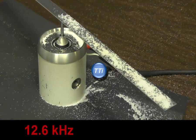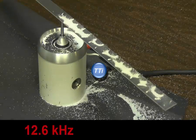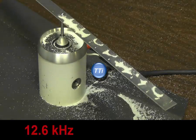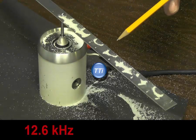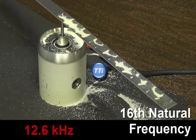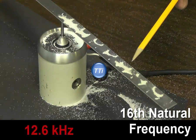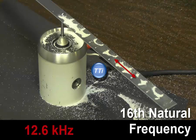Now we're driving the beam at 12.6 kilohertz. Let's apply the power to the shaker, see if we can find the nodal behavior. One, 2, 3, 4, 5, 6, 7, 8, 9, 10, 11, 12, 13, 14, 15. It looks like the 16th natural frequency, but now we're getting to such short wavelengths that we're starting to get this kind of behavior here. And look, there's a little node running up the middle. We're actually starting to see this beam act more like a plate. So let's look at some plate modes.